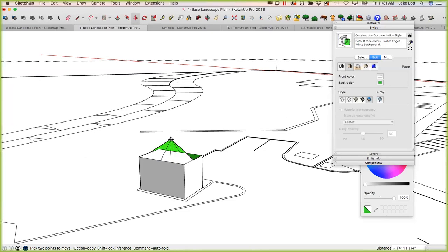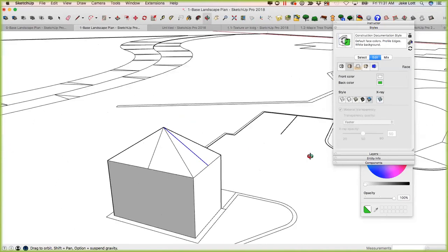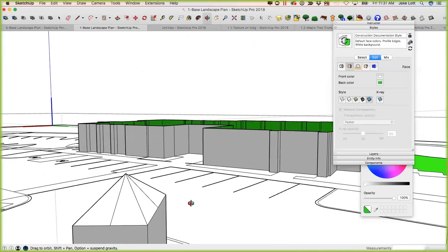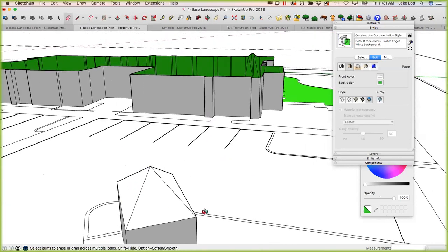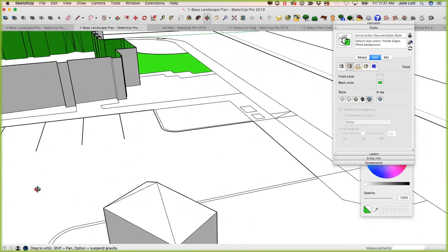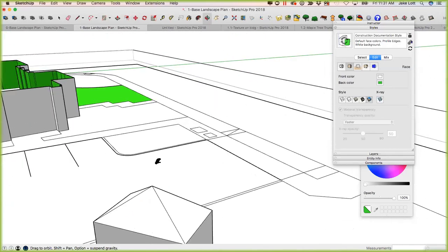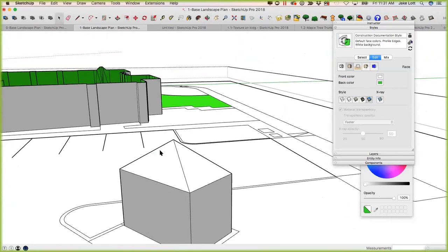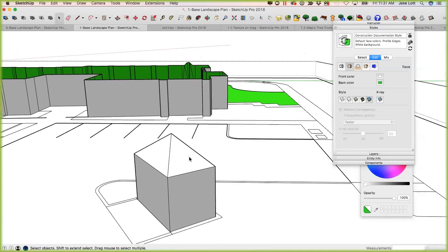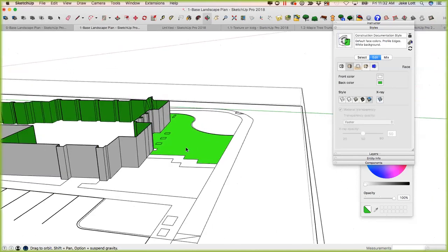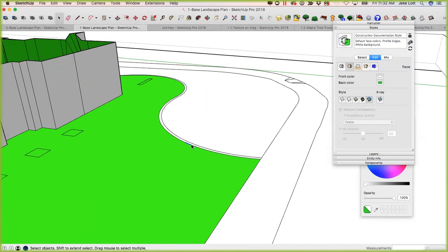Again, it's going to render the result maybe of what you wanted, maybe not. But again, we'll go ahead and drop in, actually, I'm going to make sure I go to the midpoint this time, and I'll go to the midpoint this way, and pulling up that point into the blue direction, give yourself a pitched roof on all sides. So after that's done, if the face is planar, you can remove those guidelines, and now you have that kind of position there.